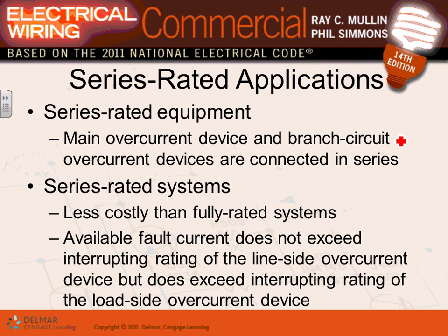What's wrong with them? Why do we care about them? Because they cost less and they're an economical application. You cannot install anything exceeding the interrupting rating of the overcurrent protection device. You can't install a lot of motors, guys, when the system is series rated.